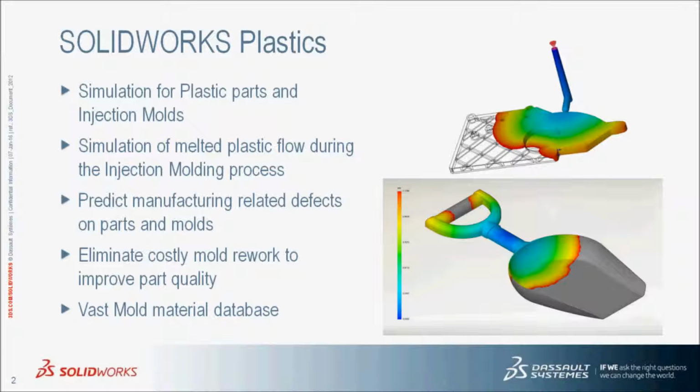Since this is fully integrated with the CAD system, the user has full control over their design and can produce quality plastic parts before the manufacturing process. The designer can predict manufacturing related defects on the parts and molds, and eliminate costly mold reworks to improve the part quality.